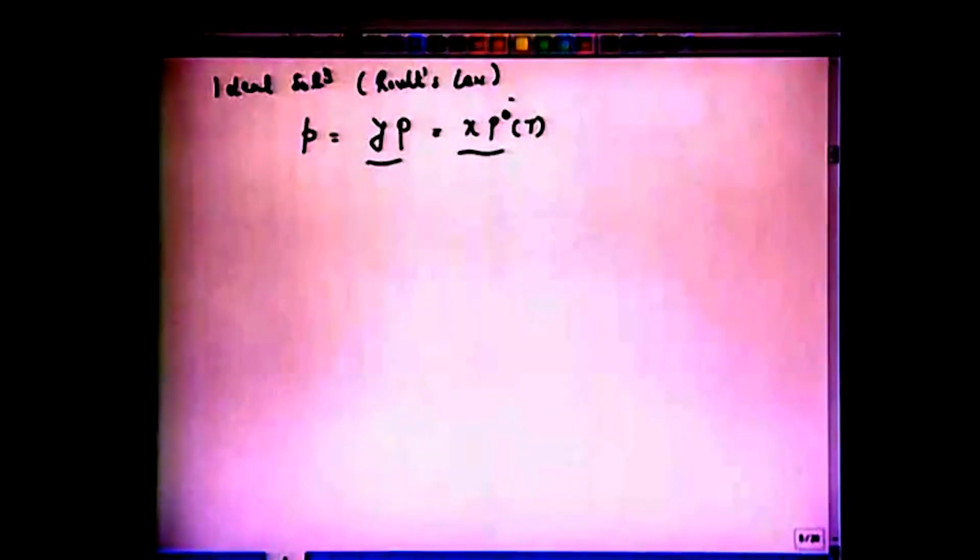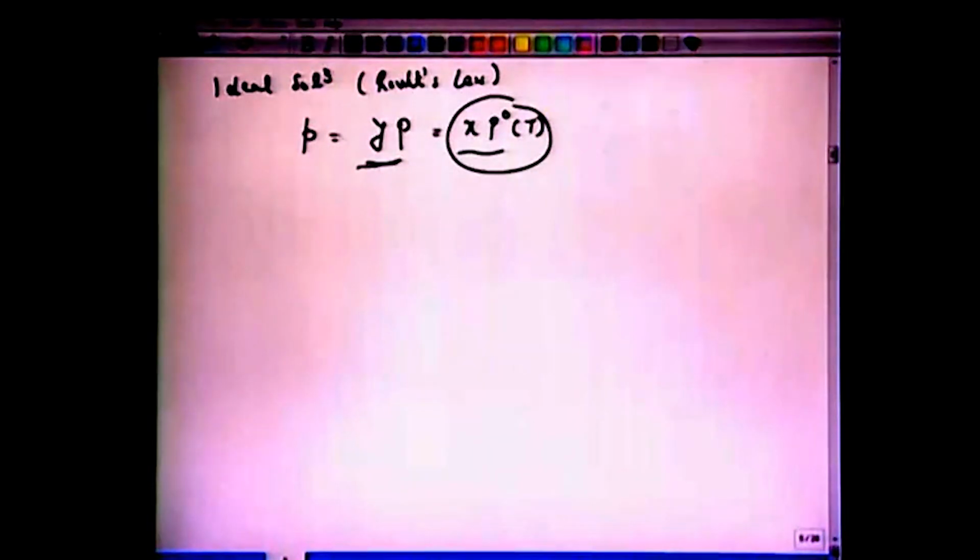So at a given temperature, which is 26 degrees centigrade here, all we have to do is find the vapor pressure of benzene, and then knowing the total pressure we can calculate this Y versus X curve. So let's write down here that we are assuming ideal solution and applying Raoult's law, which is yP equals xP0. See the difference, partial pressure equated in two phases. So this is Raoult's law, and we have equated it with yP, partial pressure, Dalton's law.